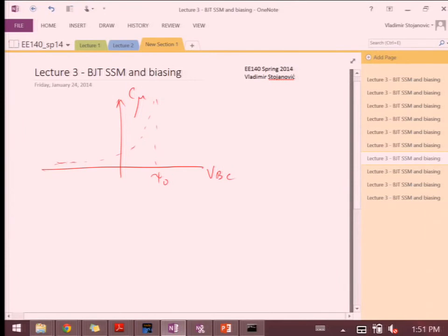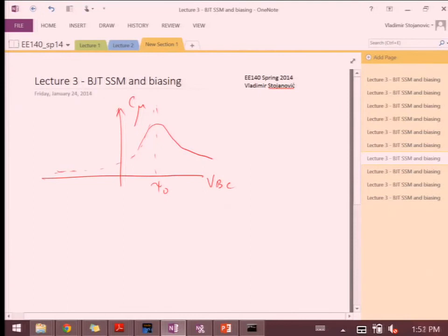This is just a curve for the reverse bias depletion cap. But if I'm entering forward bias, I'm getting a lot more minority carriers around the junction, right? And so my previous understanding that there's nothing else except the donors and acceptors forming the field is not correct. And so I have to take into account that other minority charge, and therefore it more becomes like a forward biased PN junction capacitance. So after this point, the cap starts going down, because this formula no longer applies.